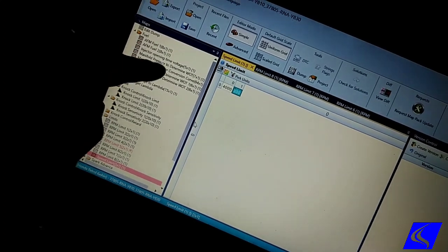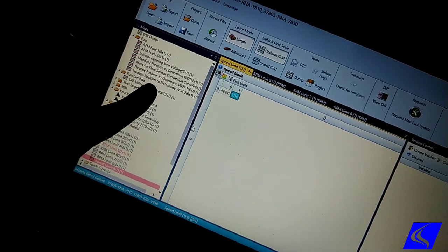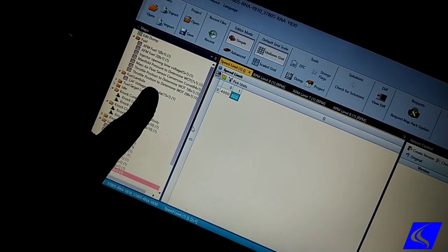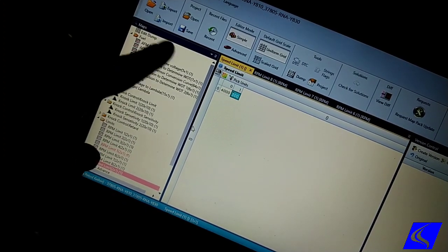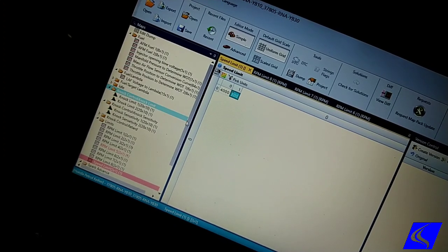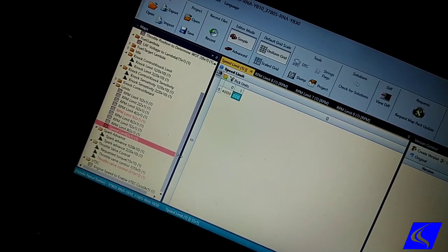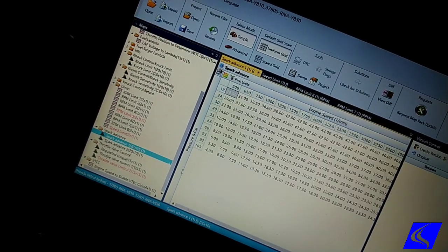This one we're going to change out after we do the baseline dyno, because my guesstimate on this one is that it lost a bunch of torque and horsepower at the low RPM because the exhaust is the wrong size. It's too big. So I will be able to adjust it once I know what the correct air-fuel ratio is. Then timing also, I will see what the air-fuel ratio is first, correct that, then adjust the timing by adjusting the spark advance table here.